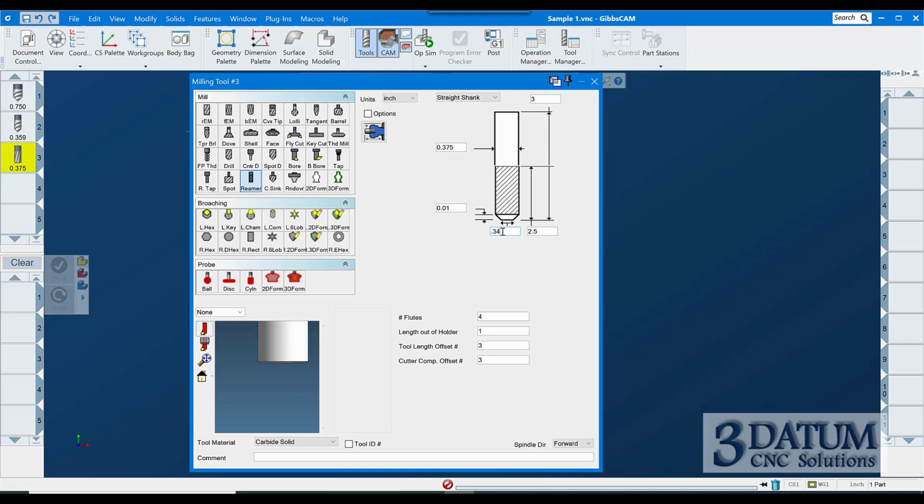So, you know, this could stay at 1 and it would be fine, but then the entire tip of that tool is considered a non-cutting surface. If you have gouge checking turned on, it will detect that as an interference. So I usually try to set this up correctly.